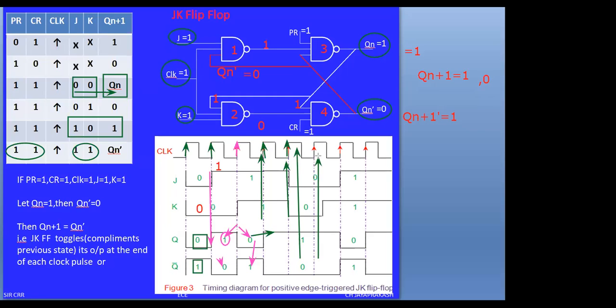During the sixth clock pulse, during this clock interval, again if you check the values of J and K, J is 0, K is 0. Therefore there is no change in the condition. The previous state 1 will be repeated. If you observe here, this 1 remains during this entire pulse, even though the value of K is modified from 0 to 1.